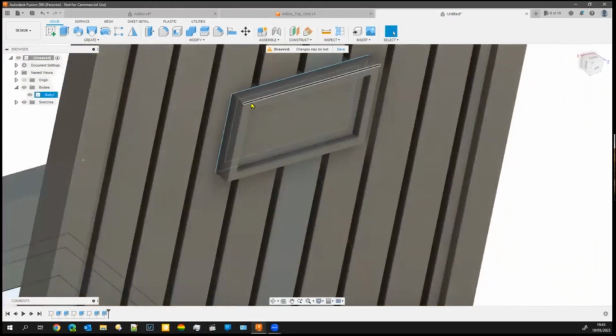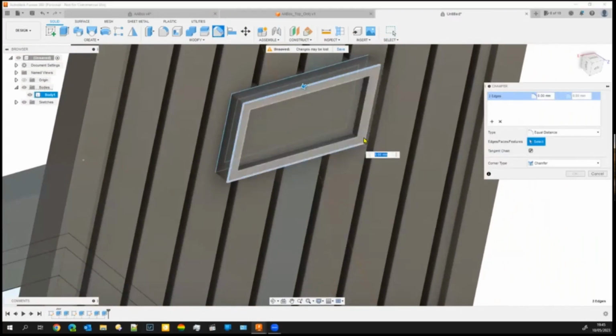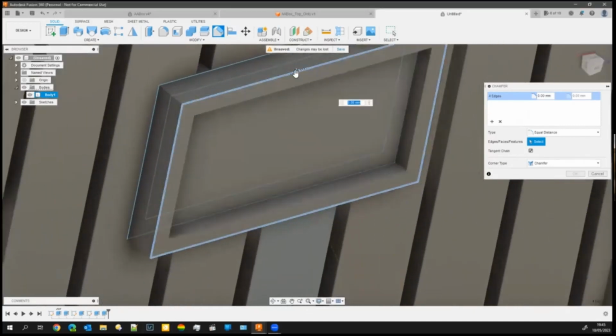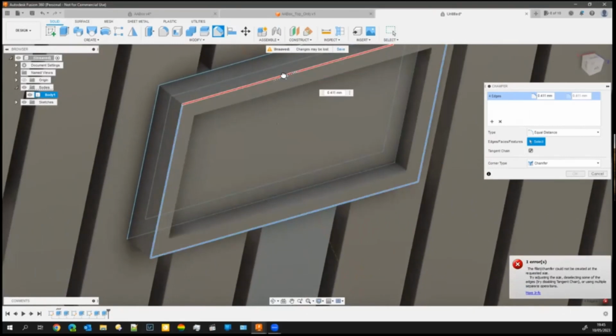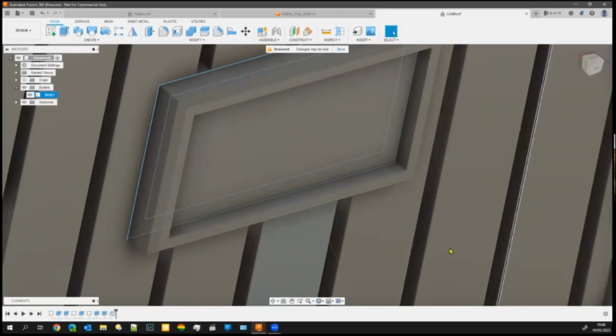Okay, next stage is to put a slight bevel on it. So we're going to pick the bevel tool, the chamfer tool, click it, then hold the shift key down to add to it. And then you can either type in an amount or just do it by eye and put a slight bevel on it. Whoops, too far. Again, if you're filament printing, you might miss that out because the filament may not actually be of a resolution to produce that.